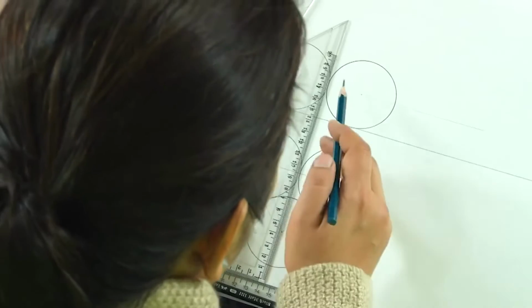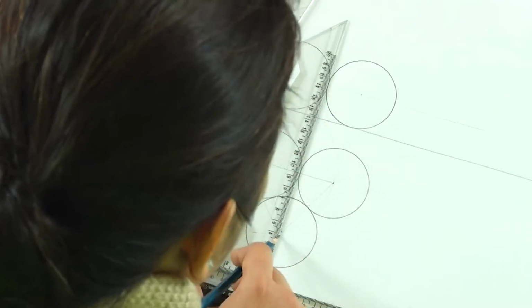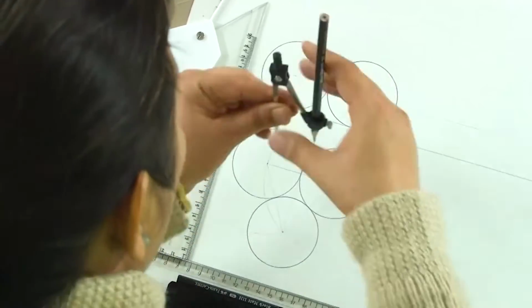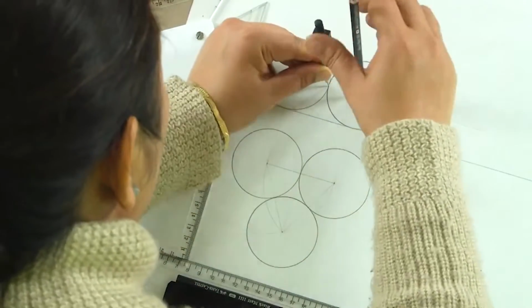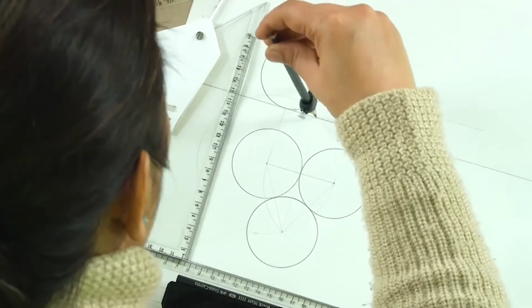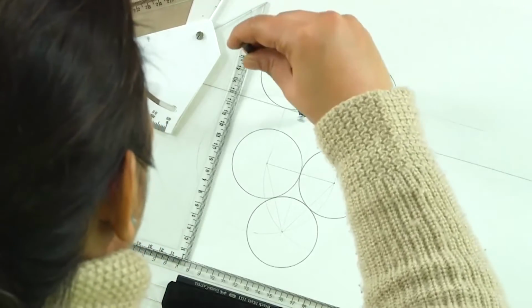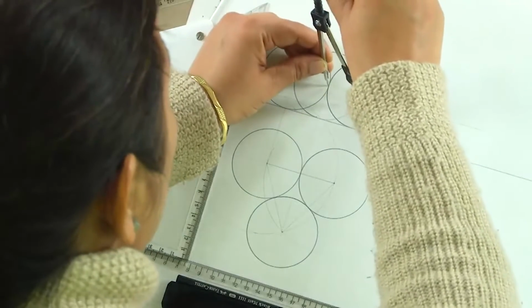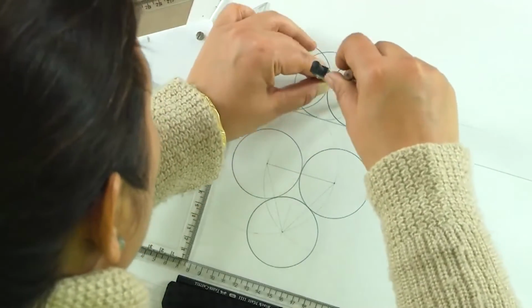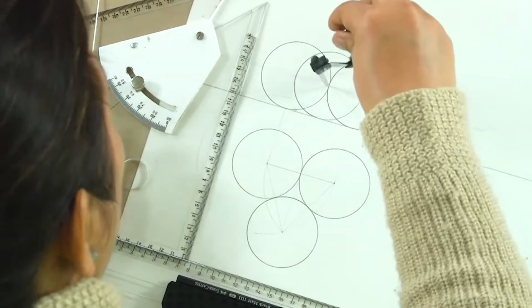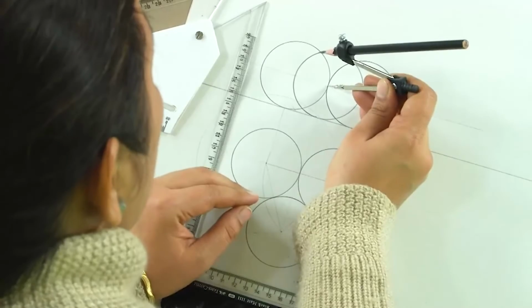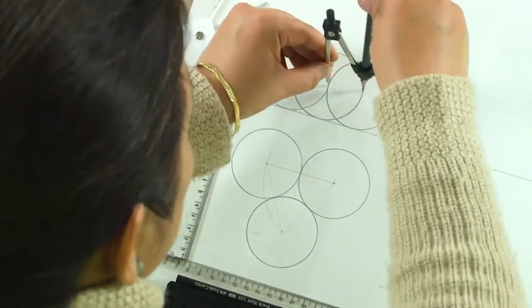And what we have is, we will just take it perpendicular, it is right in the center, and taking this one as the center, we will draw another circle. Since I am drawing on the existing drawing, I am not making a new drawing, that is why our hidden lines are actually currently depicted as the solid lines.